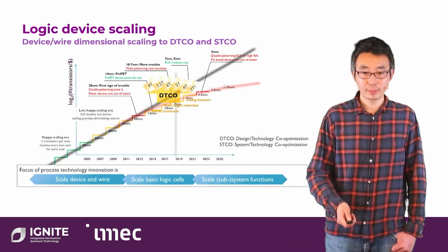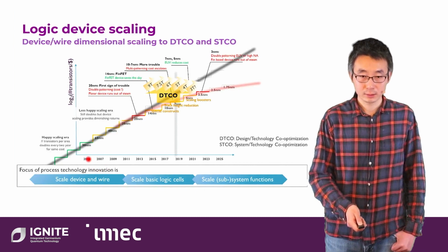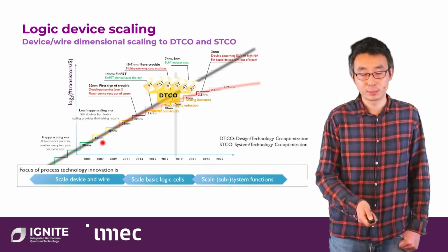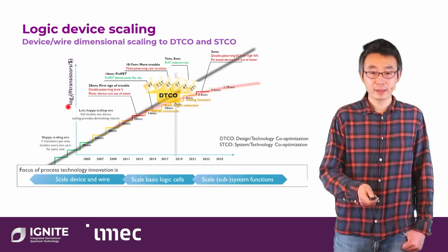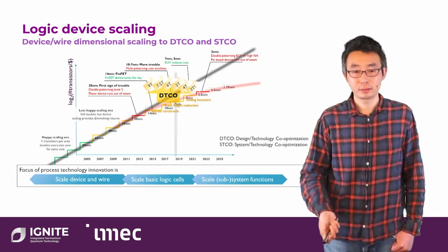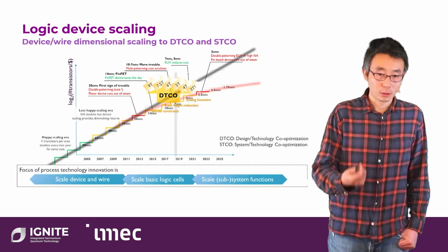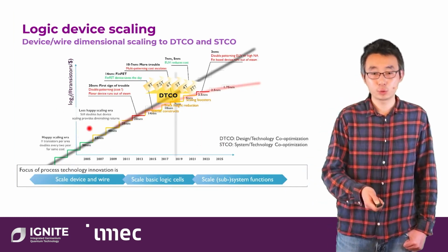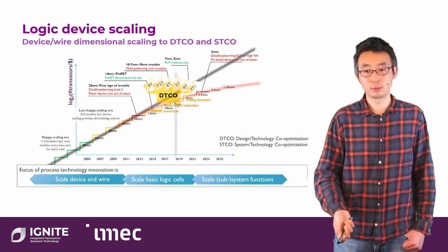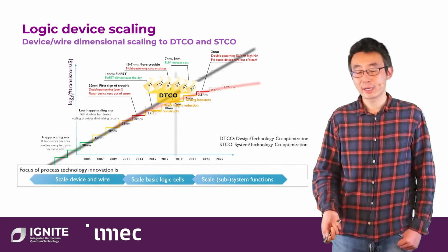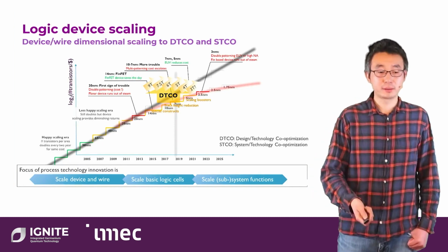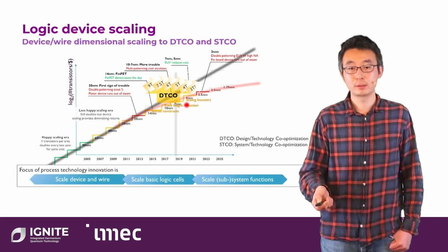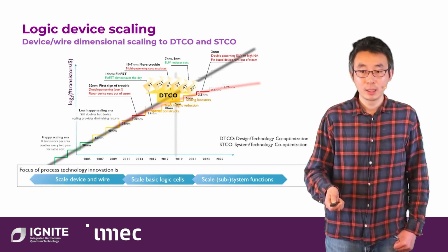So here, that's a summary page. And for the standard development of the CMOS technology, the black line, that's the prediction by Moore's law. On the x-axis is the performance of the transistor or the transistor per dollar. On the y-axis, that's the time. So on the planar region or the planar transistor region, it still more or less follows Moore's law. But when we are actually hitting the limit of different design and also material prospecting, we need to look into a different structure. So that's where the fin actually came into the picture.